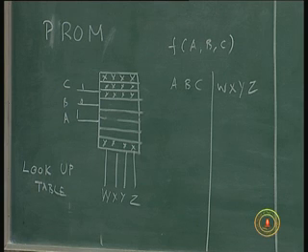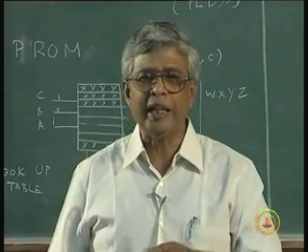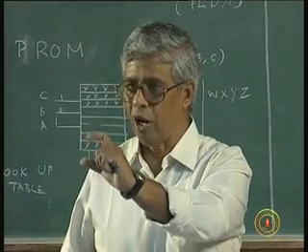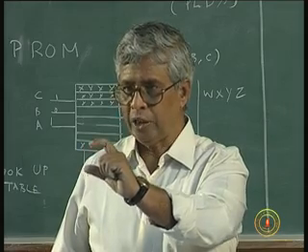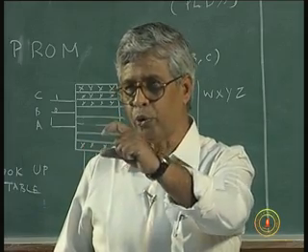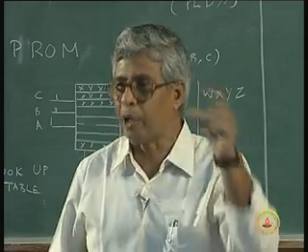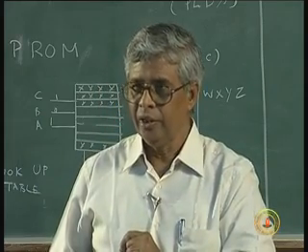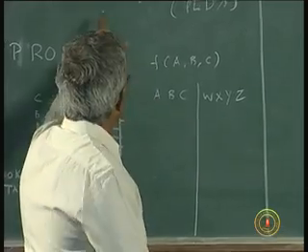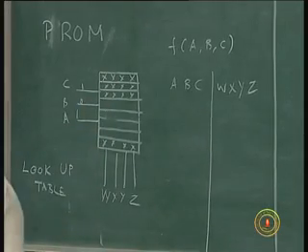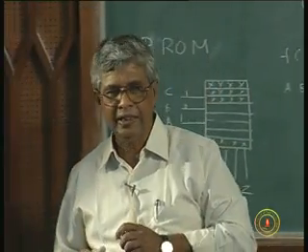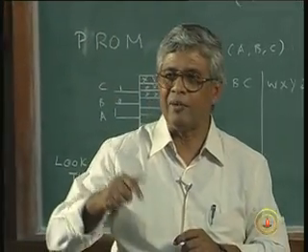So, fixed truth table is a lookup table where there is no programmability, but programmability has to be there for me to implement different functions using the same piece of ROM. Such a ROM whose content can be changed for different applications is called a PROM. PROM stands for programmable read-only memory. That is the first programmable logic device we are using. So, that is why I said PROM, programmable logic device. Many programmable logic devices we are going to discuss. The first one of them is a programmable read-only memory.